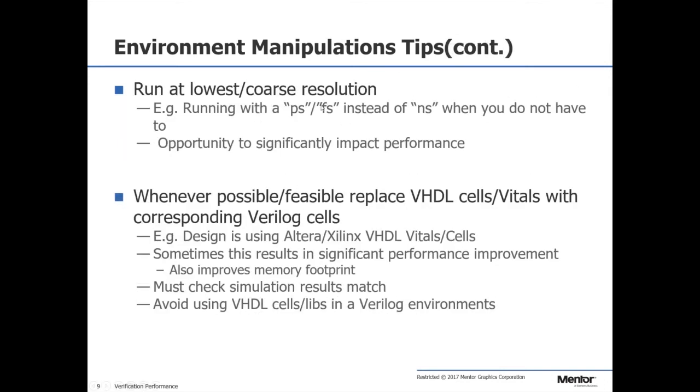Again, you want to run at the coarsest time resolution that you can. If you're running your clock rate at, say, 5 megahertz, you could probably get away with nanosecond time resolution. You won't get 1,000 times faster by using nanoseconds versus picoseconds, but again, the simulator is all scheduling based, and it's probably slightly less expensive to say wait 10 nanoseconds than wait 10,000 picoseconds. So you will see some impact by using that coarsest resolution.